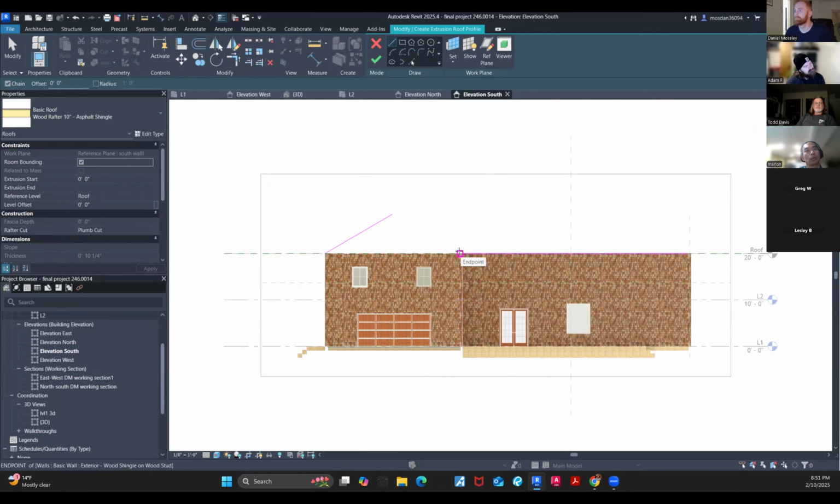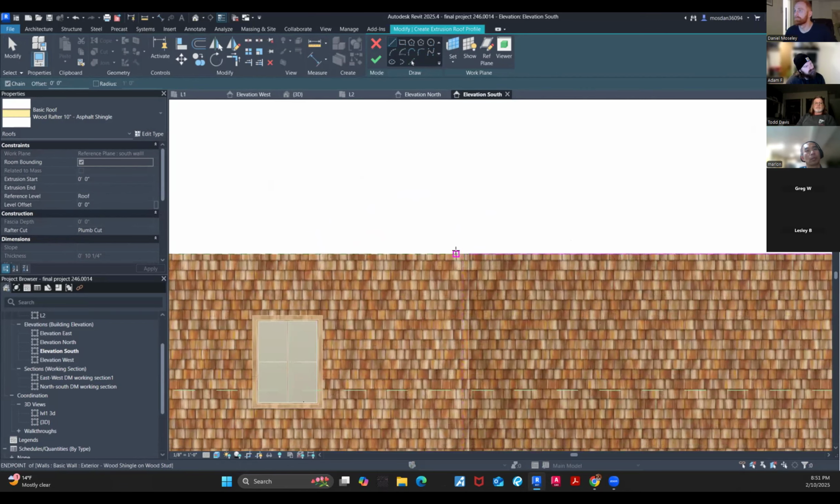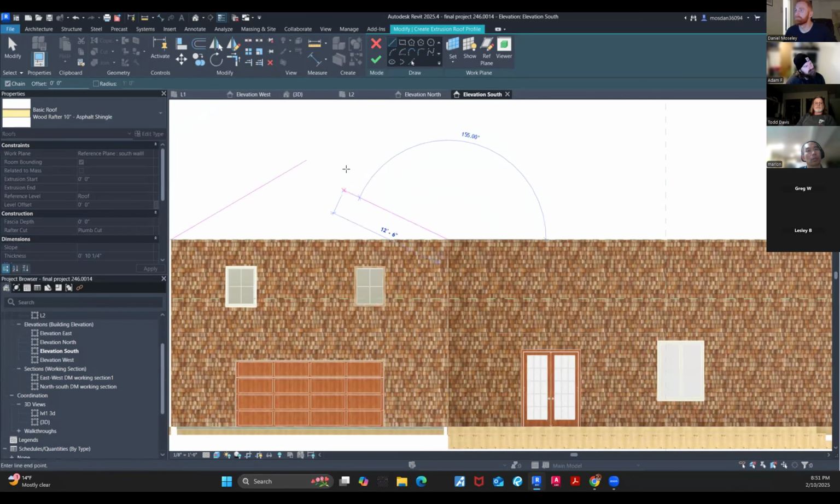So zoom in again. You're looking at this from like 60 feet out, right? Nope, keep going over. You want the line that actually. There you go. That's what you want, right there. So draw that up at a 30-degree angle. So it's going to be 150. Don't make them touch. So make it 150. It's 180 minus 30. It's the reverse. So that's 150. And now, okay, perfect right there.